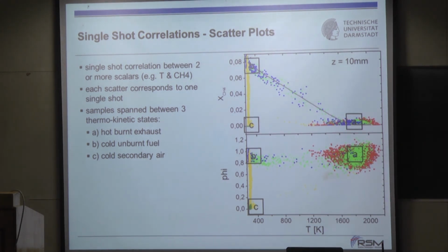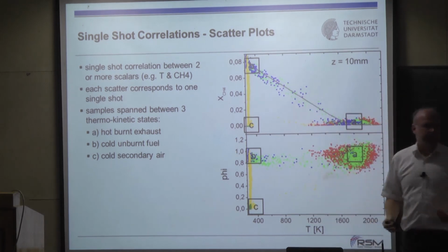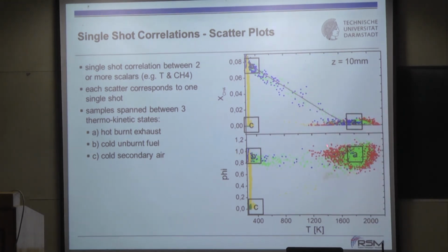The residence time, yeah. You have a flame front which is maybe only 500 microns, and you have something like a 6 millimeter long probe volume, and then you have simply less because of the lifetime of those intermediate states. It is less probable to capture them. Yeah, exactly. That's it.